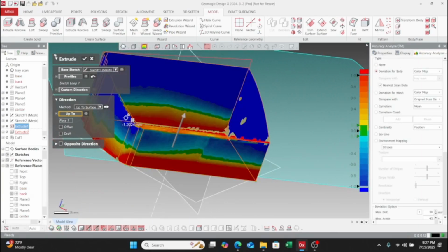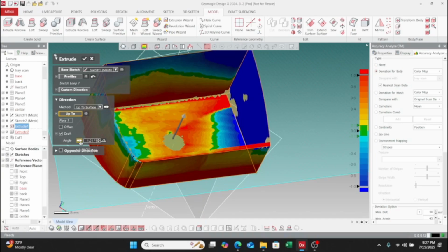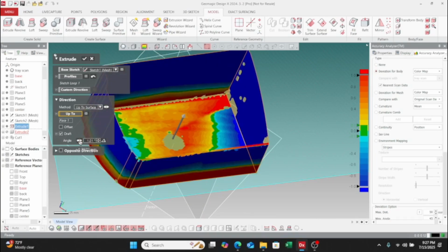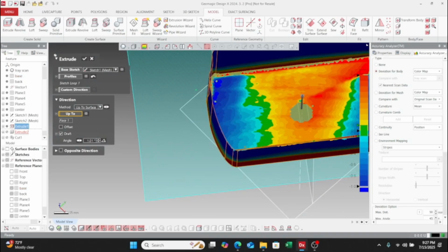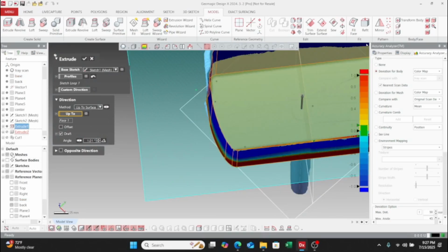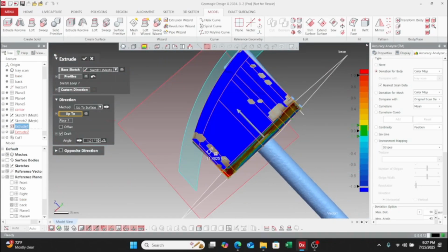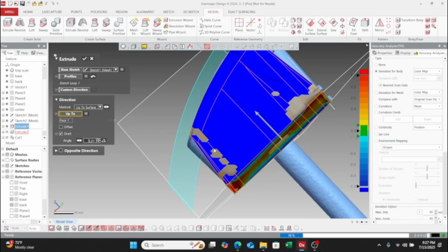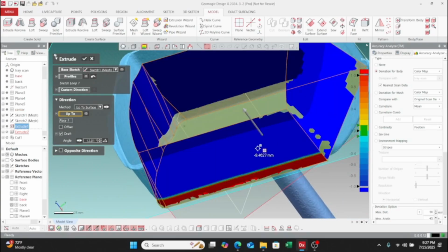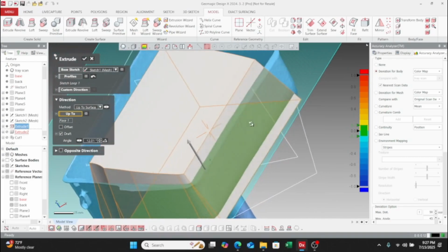And when we did that extrusion, we didn't really pay attention to the fact there's a draft on this part. And so we can go back and fix that. Software lets us do that. So kind of playing on which side here is the draft, inward or outward. You can quickly tell when we turn on the deviation colors. You know, we're really looking for green, and the green band is actually quite narrow in this case. So just to exaggerate the situation, we show what it would be like if we completely made it an inward draft, and that's obviously wrong.